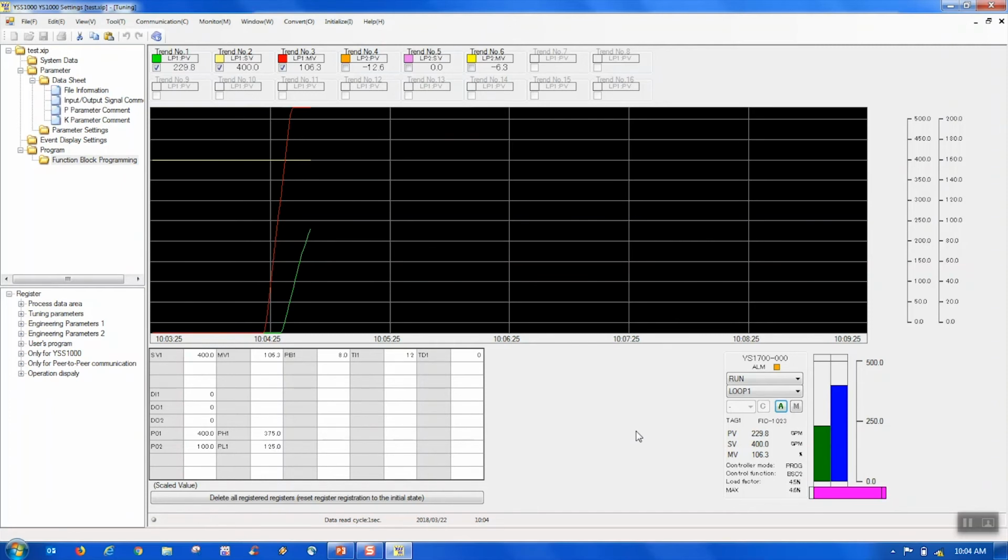We're at 100% output right now, but you'll see the flow rate rising up, and we're starting to arc just slightly as we're getting closer to the set point. We're going to cut back on the output shortly. There it goes. And we're going to ease on into the set point.